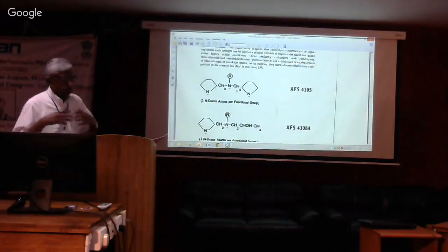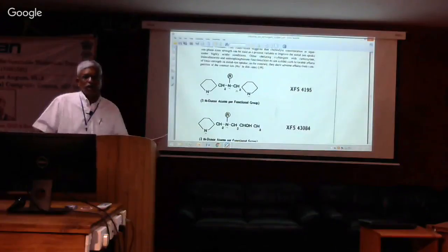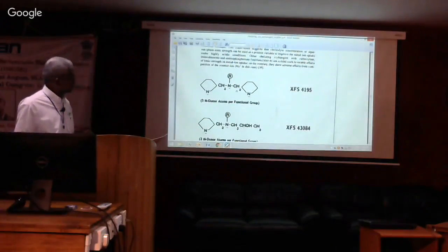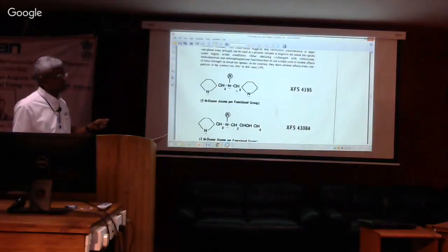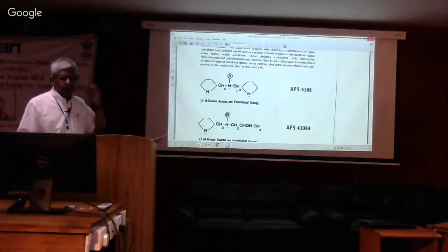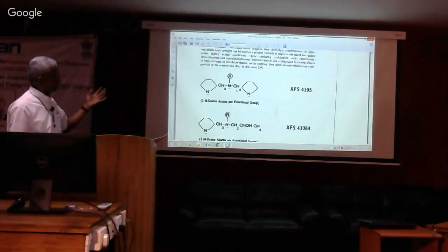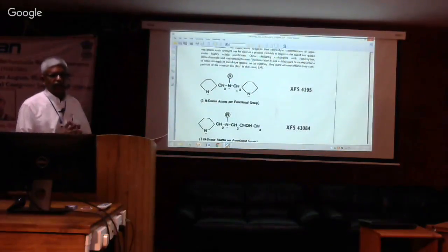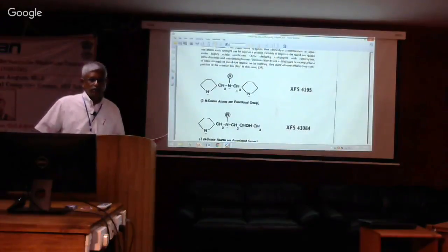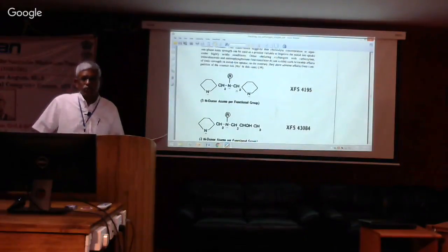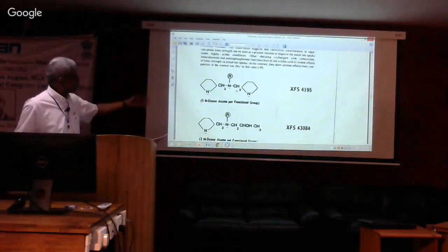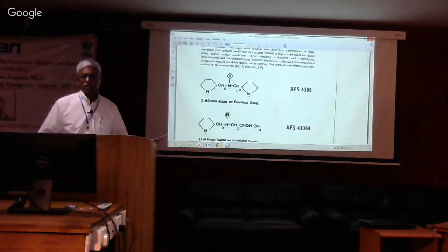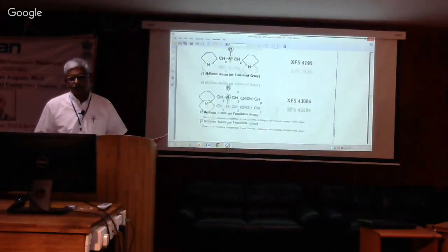We have to use a model where we are inputting these metal-ligand stability constants, and then we have to look at what would be the best resin. And sometimes our choice is very restricted. If I have, as we do in some hydrometallurgical cases, pH of 2, pH of 1, then we don't have much choice except these two resins, commercially speaking.